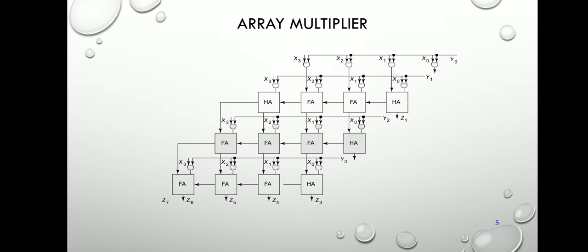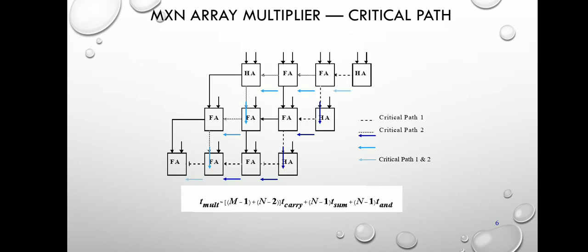To implement the array multiplier, we use the following process. First, the multiplier bits B1 and B0 produce the partial products. The first partial product is formed by multiplying A and B. This multiplication of two bits produces a 1 if both the inputs are 1, otherwise it is 0. This is identical to the AND operation and can be implemented with an AND gate. This product is formed by means of two AND gates, and the partial product can be multiplied by the A and the B, which is shifted one position to the left.